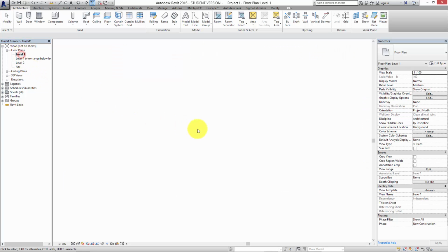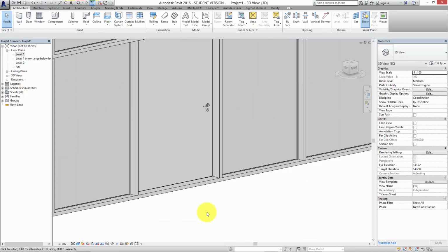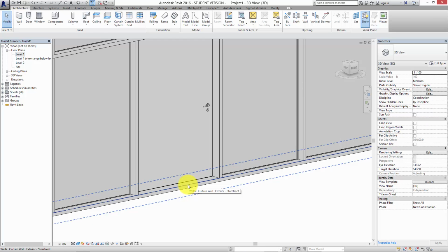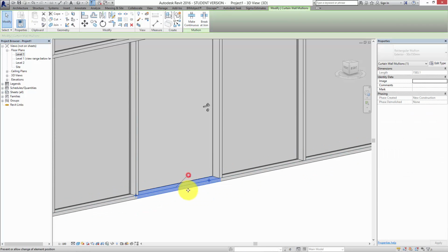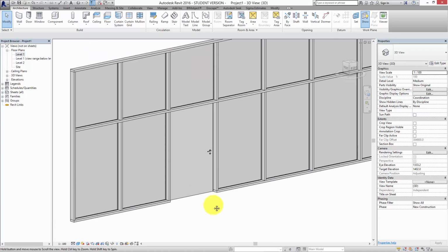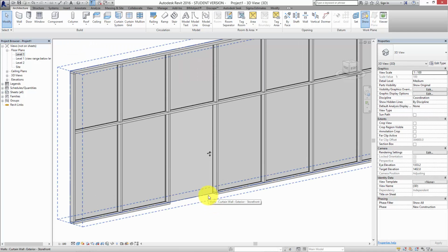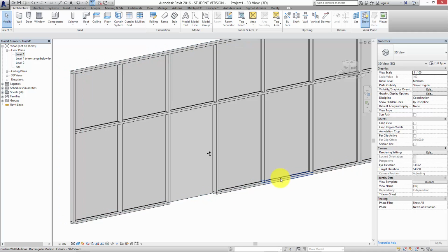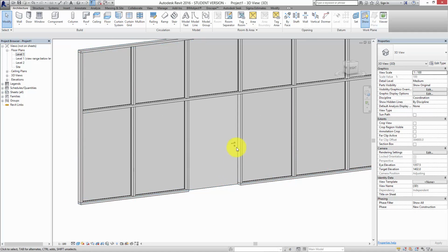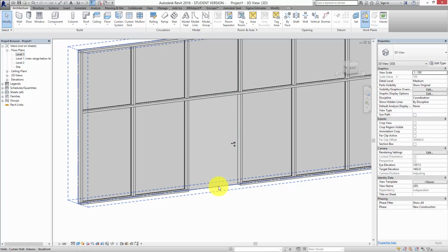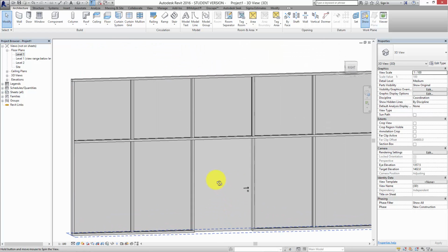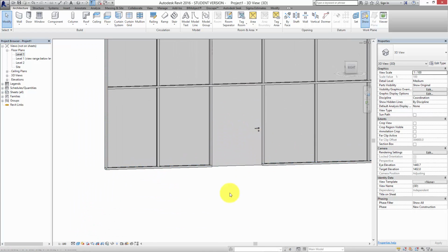It looks the same. It's kind of confusing, but it looks the same. It gives us the door swing and everything in there. But it's actually a curtain wall panel. But I can then go through and say, well, I don't need this mullion on the bottom because it's a door, and you can quickly go through and modify the panels that way. But it doesn't have the frame around it. The guy who made the door panel didn't put a frame around it. So you could come in here and add one that had an extra frame, but it could be built as part of the curtain wall.